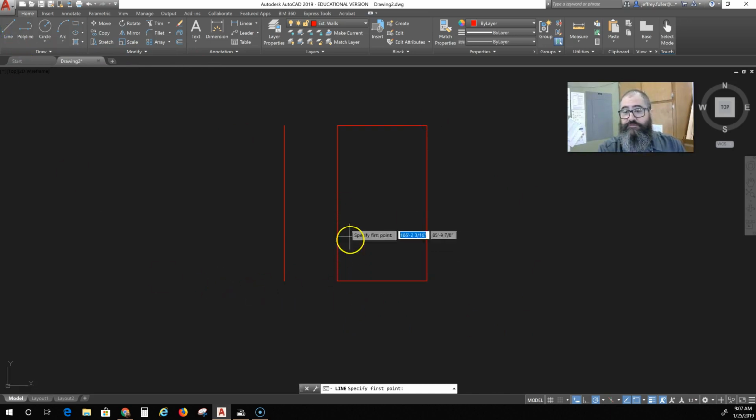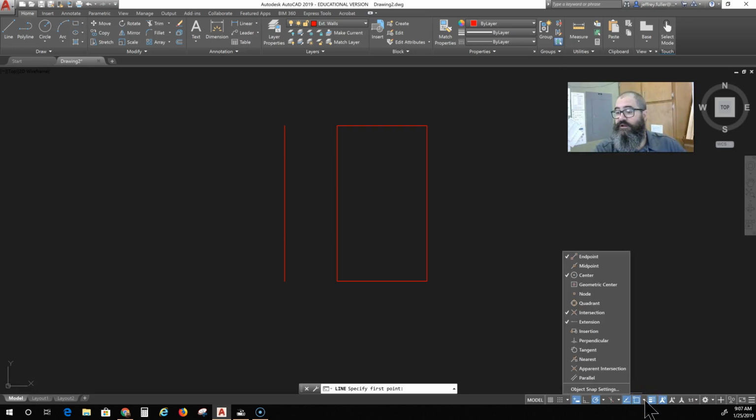This is actually going to set back a little bit in this section, so this is where it gets kind of tricky. You have to turn on that grip point and/or turn off your end points. I like to keep my end points on, and that is done down here on the right where I'm circling. If I hover, it says snap cursor to 2D reference points. Click on the little arrow and you get your menu of what you can snap to.